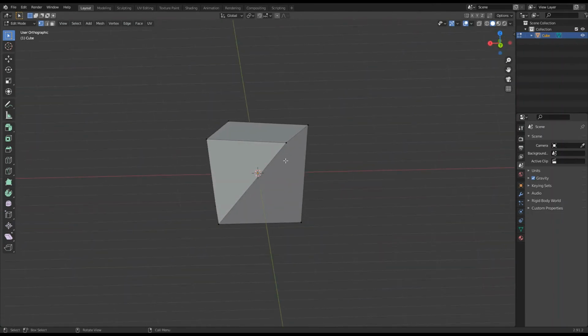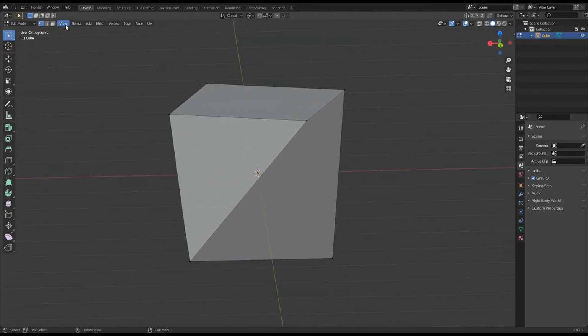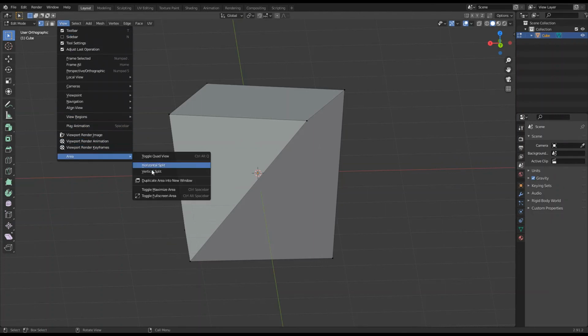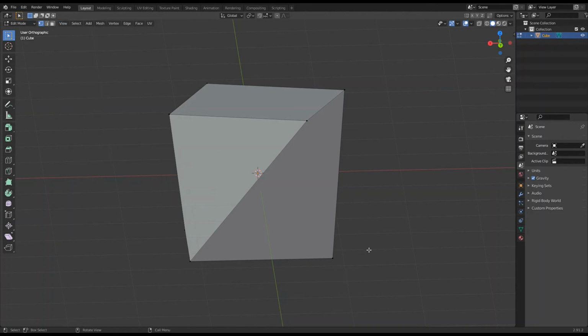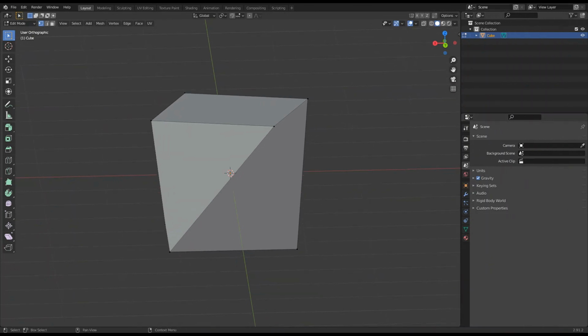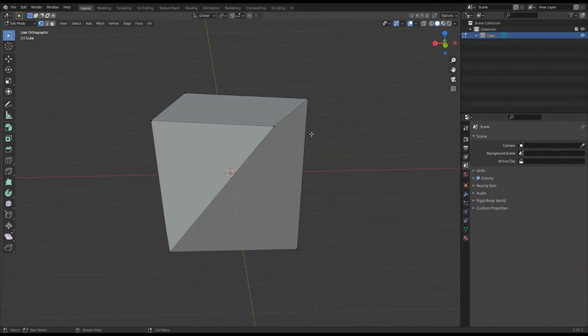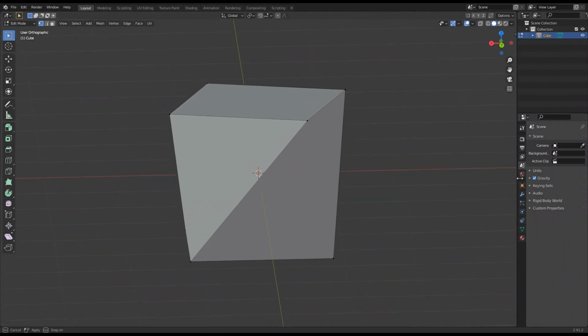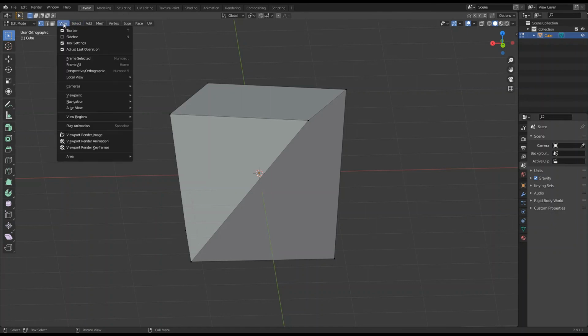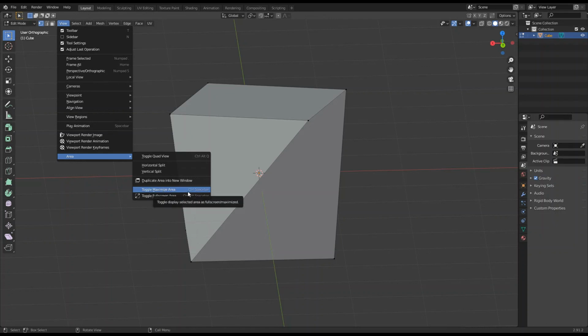And then another thing that can be useful, if we go back as a reminder on how to find it, is Areas. This one says Toggle Maximize Area and Control Space. So if by any chance you had a massive amount of stuff up here and this was getting quite compacted and you wanted to really look at this window, it was Control Spacebar and it goes into full screen. Okay, to get out of that, Control Spacebar. The reminder for that was View, Area, and it's the bottom one, Toggle Maximize Area, Control Spacebar.